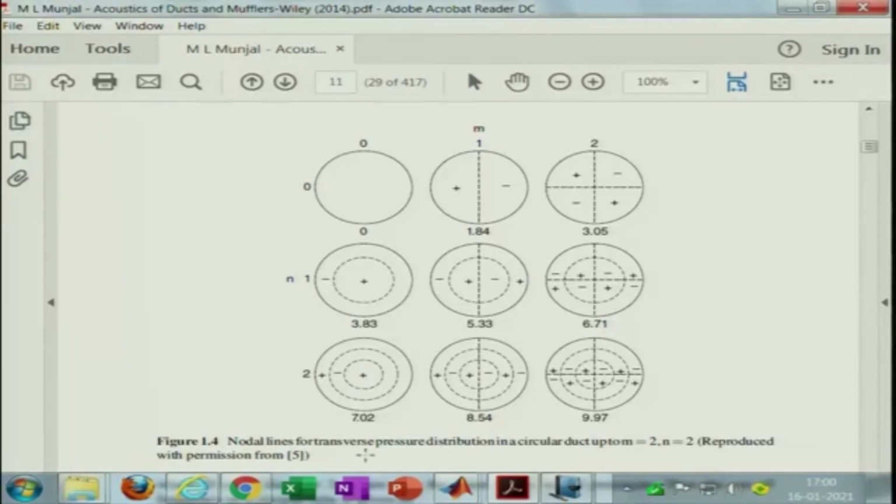So, these modes are called axisymmetric modes, also known as the radial modes, where I am pointing in this direction. They have no theta dependence, they only show variation along the radial direction. So, whatever angle you go, you have the same pressure value, but if you go along a particular circle, you have 0 variation, and these dotted lines are the nodes. These are called pressure nodal circles. So, at this radius, pressure is identically 0 and they are alternating phases. Similarly here we have two nodal circles.